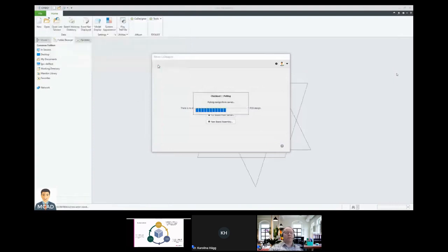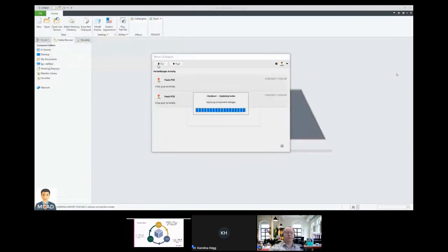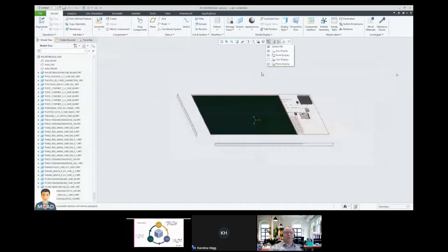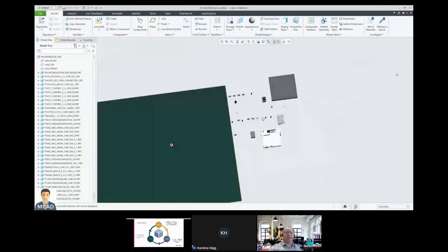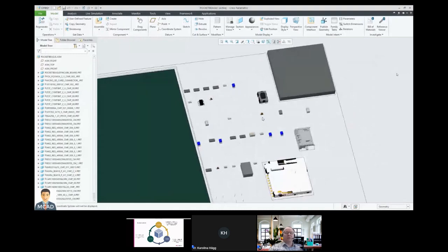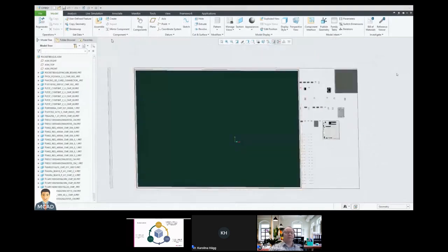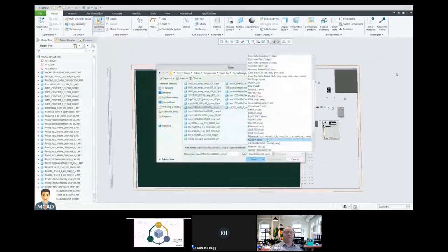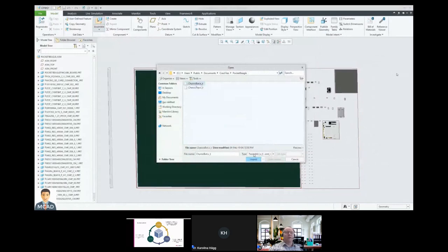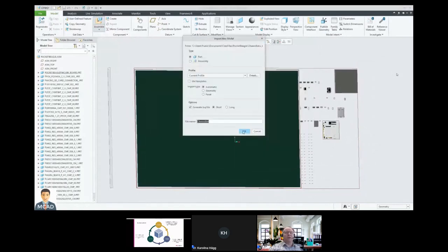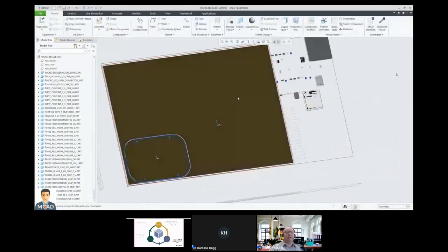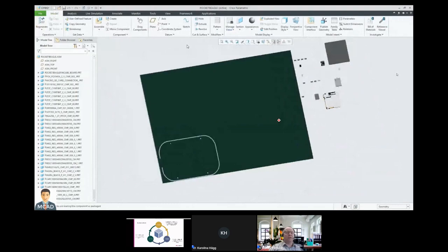Creo Parametric this time. And it's creating a new 3D assembly from the information from Altium Designer in this case. As you can see, the PCB board is just a flat surface, and then we have the biggest components just placed there, and now the mechanical engineer needs to start modifying the design by creating the right shape for our board. He's importing first the enclosure where the board needs to fit in, putting that in place and then modifying the board geometry so that it fits into the enclosure used this time.